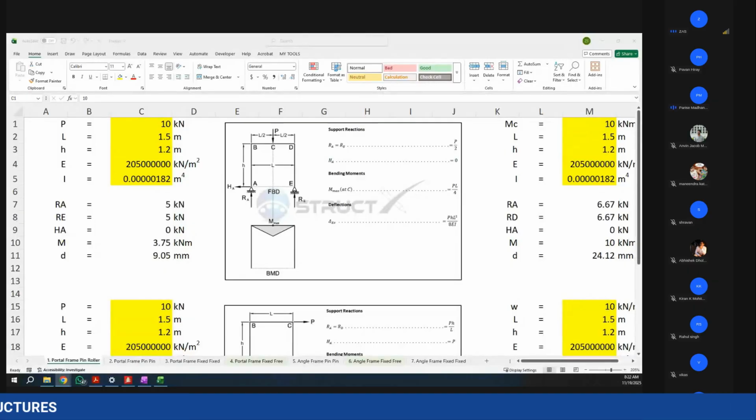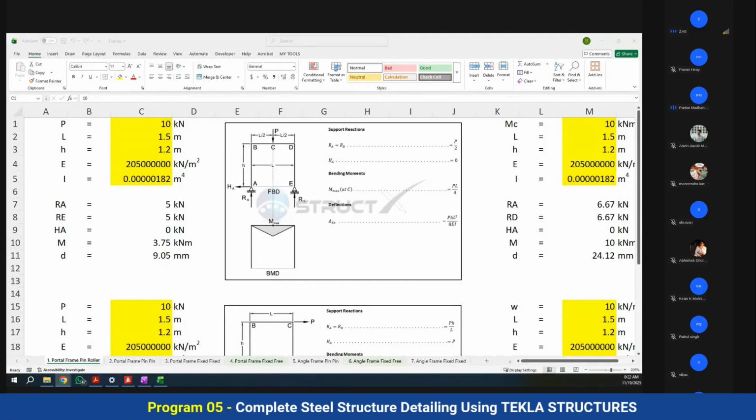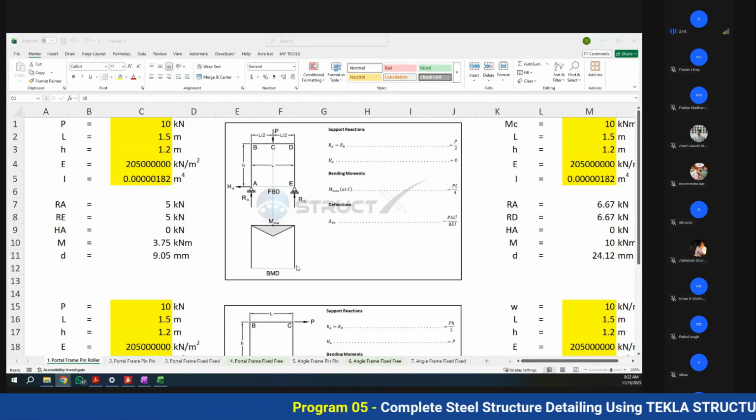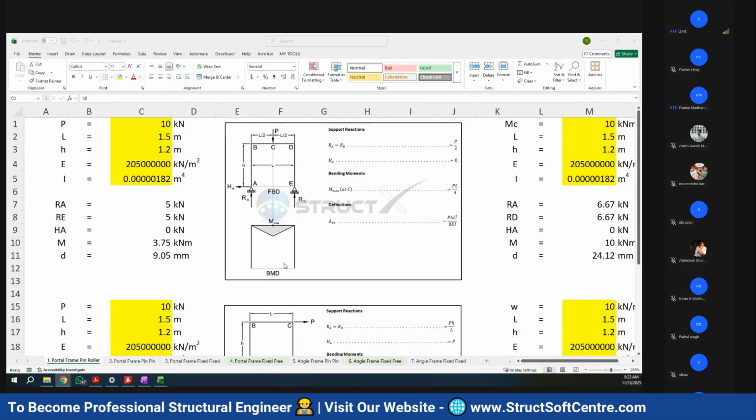When we place the load on the beam, it will drag both the columns in, so it will show like that in STAAD.Pro. So which is correct, STAAD.Pro or the manual calculation? As per my point of view, STAAD.Pro is also correct. In the manual calculation, we will see only the load on the beam, not on the columns. So instead, it's showing both loads.